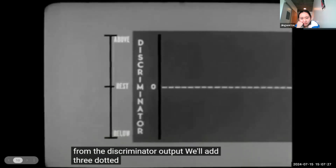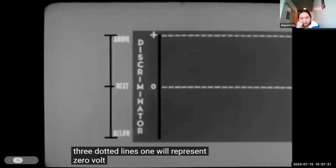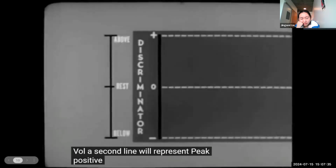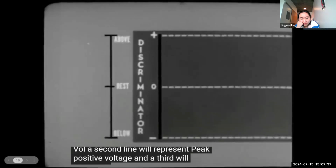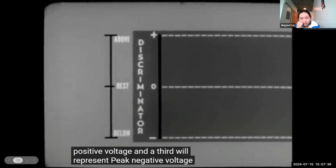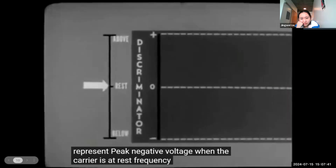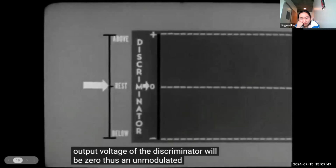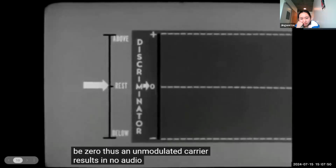We'll add 3 dotted lines. One will represent 0 voltage. A second line will represent peak positive voltage, and a third will represent peak negative voltage. When the carrier is at rest frequency, the audio output voltage of the discriminator will be 0. Thus, an unmodulated carrier results in no audio signal.